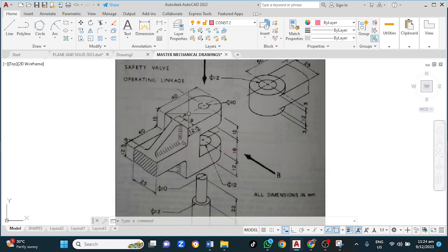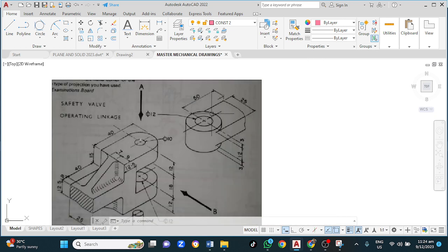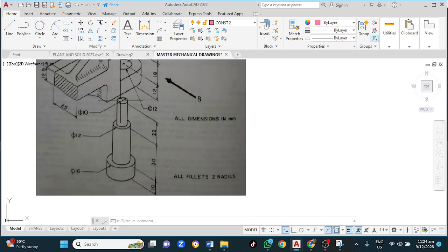The cutting plane will be taken from here. We will be cutting this through the center of this, through this hole, and all the way down. In like manner, here we'll cut along the center as well. Also the shaft will be cut along here.